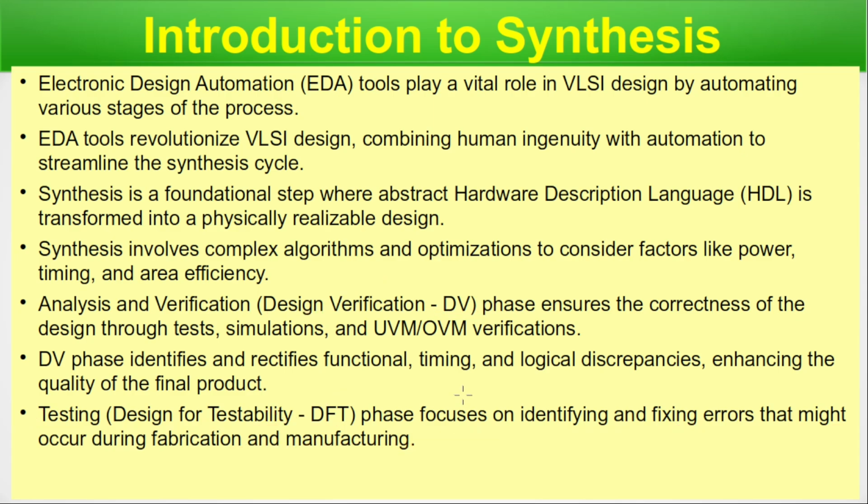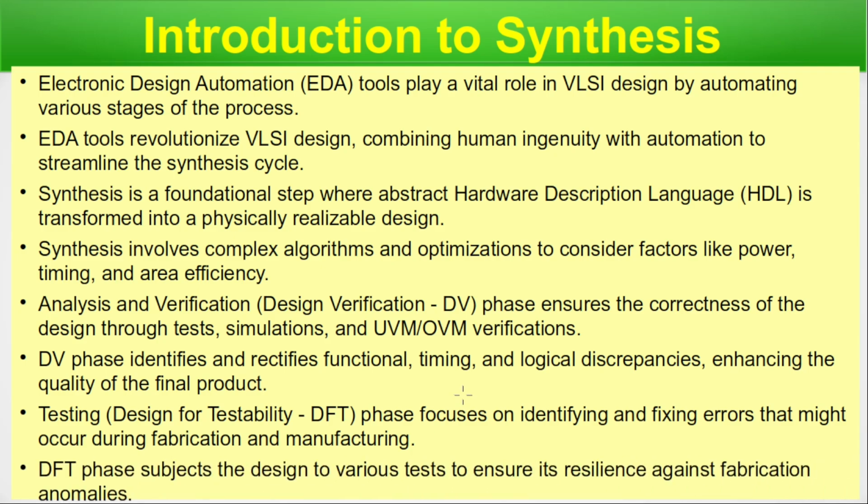We kept all the concepts of the front end part here in this introduction because you should not confuse synthesis with any other front end steps, especially the DV or the DFT, that is the design verification or the design for testing. The DFT phase subjects the design to various tests and ensures resilience against fabrication anomalies. So the DFT ensures that the final product is good and all the fault testing is done before we leave the front end. Every aspect of the front end is verified and done.